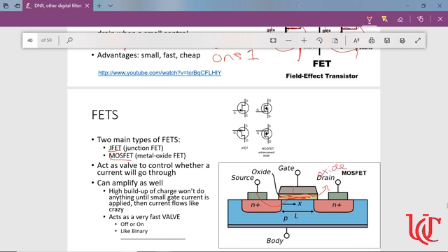Remember we talked about the difference between silicon and silica is whether it has oxygen on it. That oxygen is pretty insulative to wanting current to flow through it versus our base forms. And so if I have an oxide layer, that acts like a pretty good insulating barrier. I can still detect that charge, so it still helps overcome the negative charges that would build up, in this case in my P-type, and allow current to flow, but it won't allow current to flow this way. It just helps overcome that negative charge on the body of my transistor. That's what's called a MOSFET, so it's a metal oxide barrier at the gate.